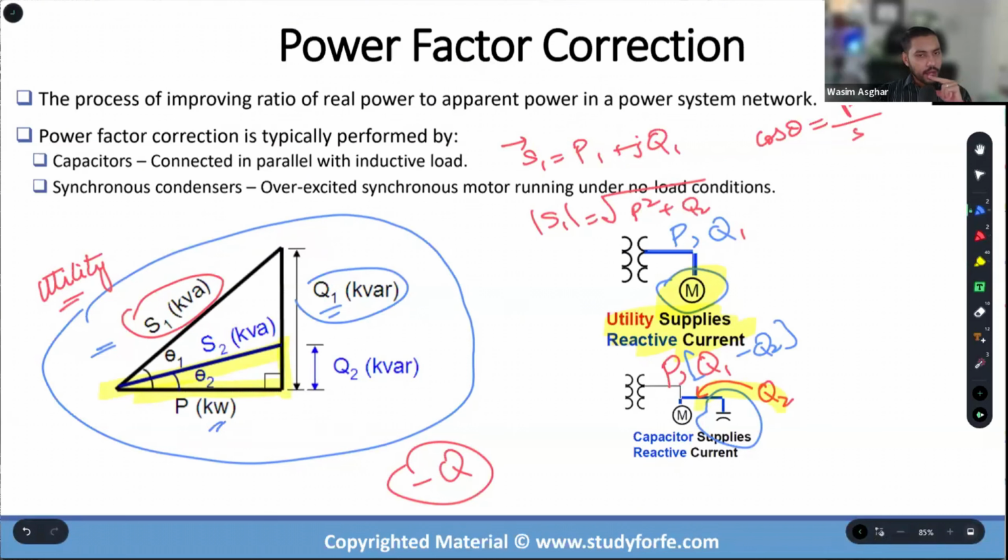The triangle, right? Your apparent power triangle, your power triangle in short, has a very low amount of Q requirement because you are able to provide a lot more reactive power locally. Actually, what the capacitor was able to provide is this delta Q. Okay, let me correct this. So the capacitor provided delta Q, right?